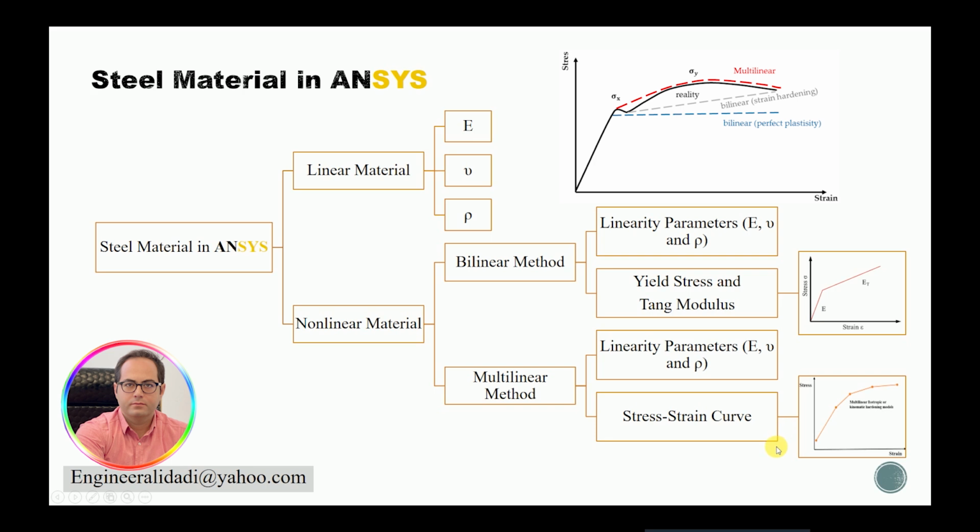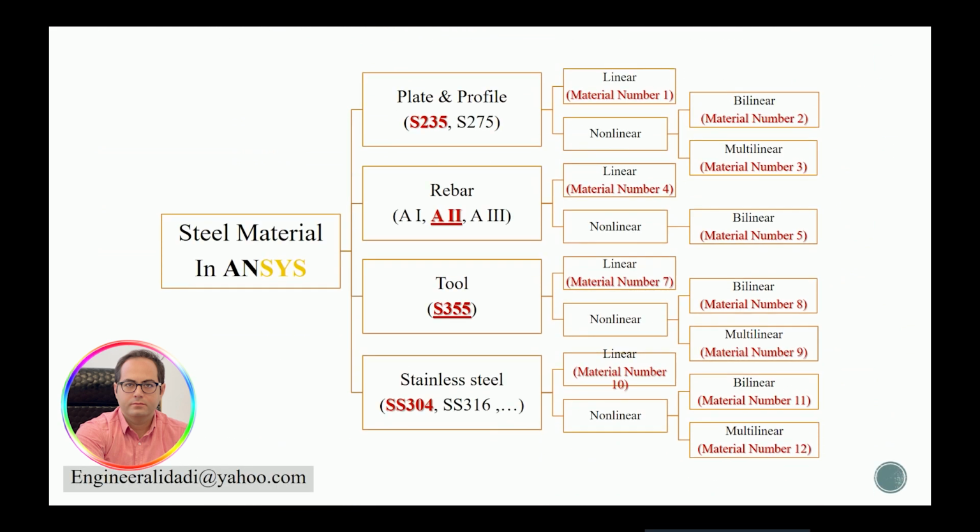The most important point in defining this stress-strain curve in Ansys is the coordinate of the first point of the diagram, which must be according to Hooke's law. I will present these calculations to you in the Ansys APDL Graphical User Interface environment and in Ansys commands.